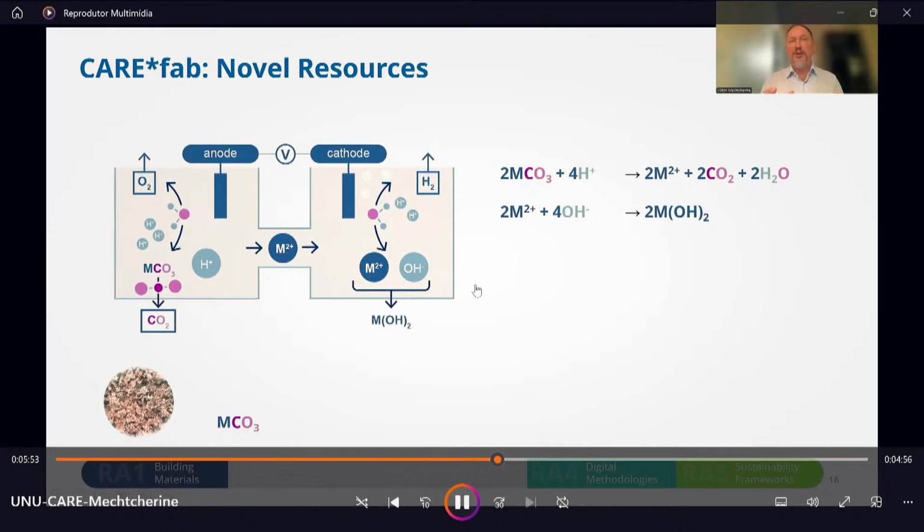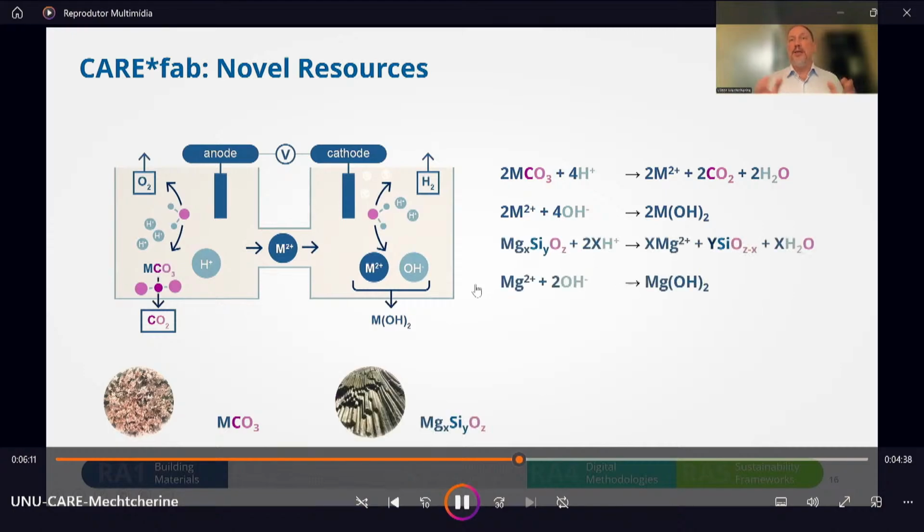During binder formation, hydrogen and CO2 are released separately. The hydrogen can be used as fuel, while CO2 will be used as reactant to synthesize polymers or for carbonation of mineral binders. When using magnesium silicate and other minerals such as olivines, this method enables cement production without any CO2 emissions. The resulting mineral binders can furthermore act as CO2 sinks, paving the way for CO2 negative concrete.